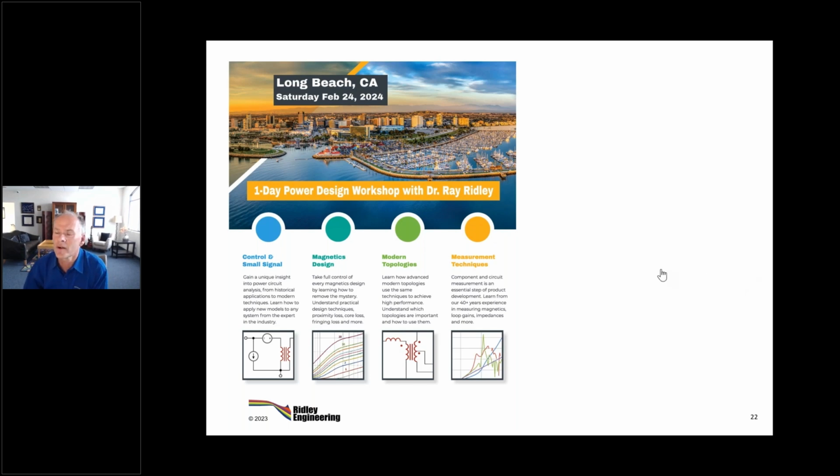Does the Ridley box use square voltages? No, it uses sine waves. Everybody uses sine waves. All the test data for the core material is a sine wave. However, the model for core loss can take the sine wave data, and then you can apply a square wave to it, and you can watch the dissipation change. It doesn't care what the waveform is. It can be a sine wave, it can be any waveform you like. And of course, normally it's a modified square wave driving it, which is a modified triangle wave in the current and the delta B.